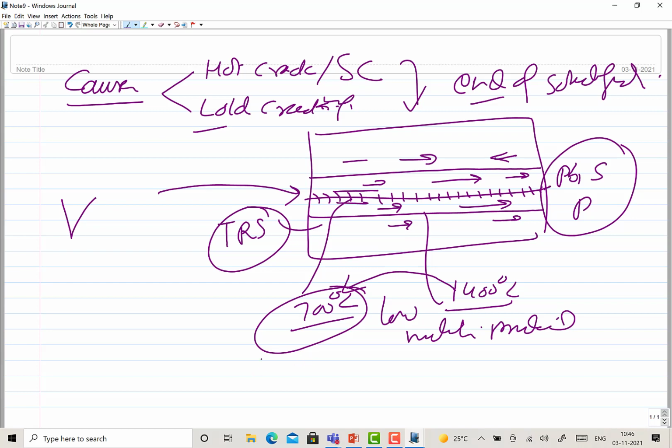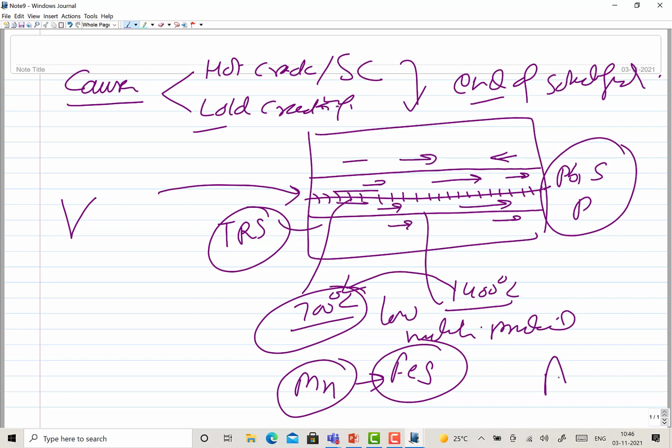So the best remedy to avoid these cracks, especially in steel welding, is addition of manganese. So the manganese takes care of the formation of the low melting point constituents like iron sulfide formation. So sulfur. And this problem is more pronounced in austenitic stainless steel welding. So there, addition of manganese, addition of some ferritic fillers helps, as that acts as, you can say, a sink or storage for phosphorus and sulfur kind of impurities.